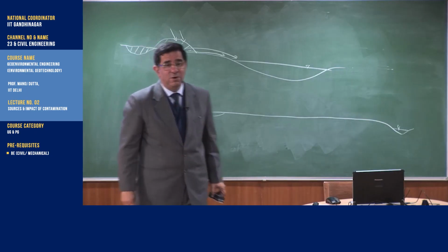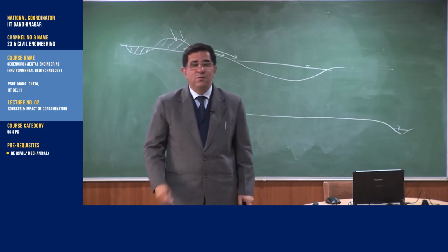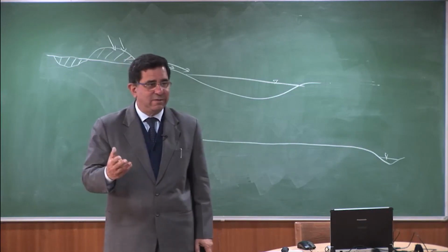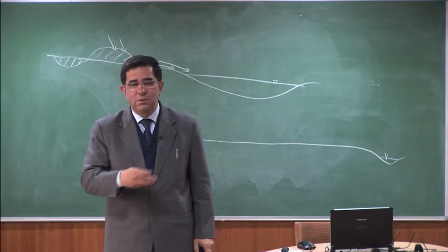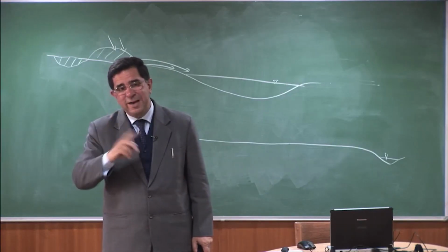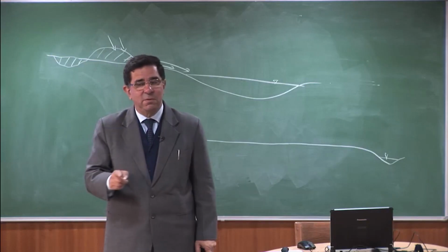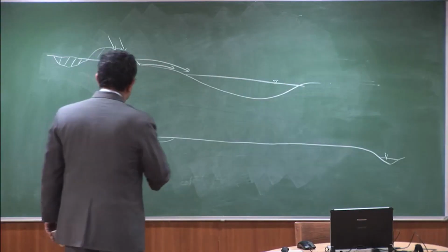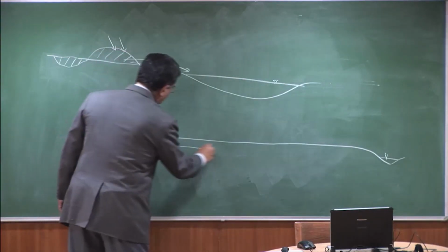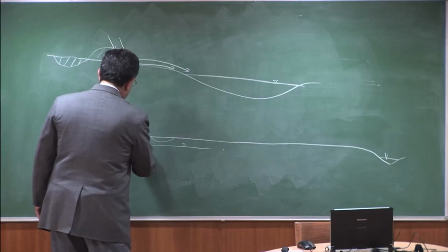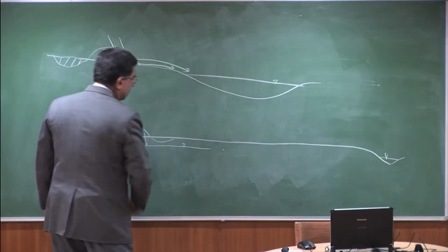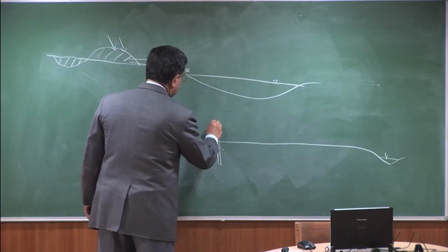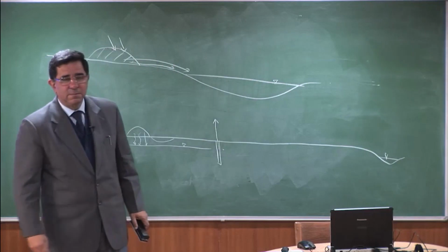What kind of soil are we sitting on in Delhi? It's alluvial, sandy silt, silty sand. It's not pure silt. We call it Delhi silt sometimes, erroneously. But if you were to give it an engineering classification, it is silty sand, sandy silt. So is it a permeable soil or an impervious soil? The answer is right there, staring at you in the face: if you are sitting on pervious soil and if the groundwater is not deep below, and God forbid if you have a tube well or a pump here which extracts the water, then you are going to receive it.